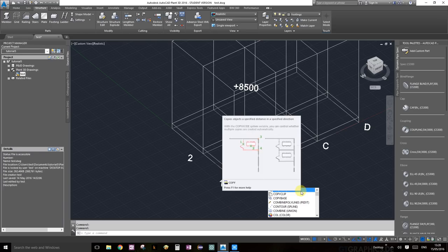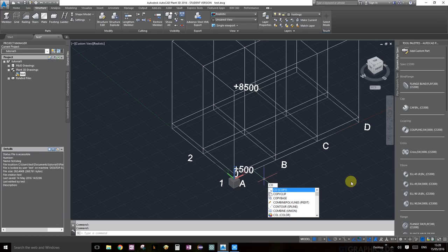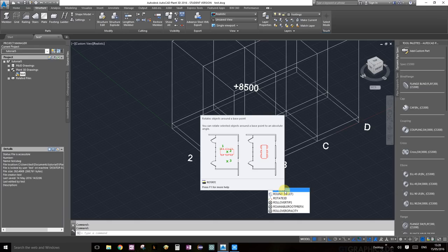One thing awesome about AutoCAD is anytime you want to do something, let's say you want to rotate something, just start typing. You don't have to select anything. Type RO, and see, rotate shows up. It will show up right by the cursor, and so you can choose which one applies to you and read the command line. It would give you instruction on how to do it, or if you just hover your mouse over it, it'll give you more information. And if you wait a couple of seconds, you'll get even bigger information, as you can see on the screen.